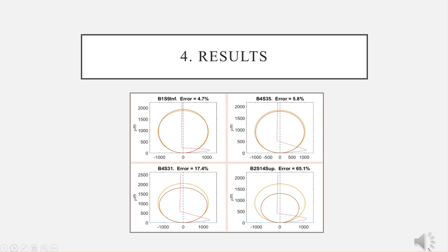Finally, we attempted to simulate not only the fatigue life, but also the crack front evolution. In particular, the process by which embedded elliptical cracks approach the free surface of the specimen and turn into superficial semi-elliptical cracks is of great interest, since most of the specimen's fatigue life was associated to embedded elliptical growth, and thus this transition from embedded to superficial crack usually means that final failure is very close.